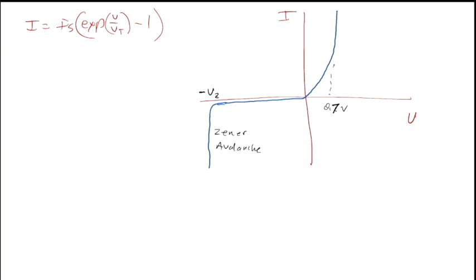There are different effects, and they occur at about the same voltage, and some devices have more Zener breakdown, some have more avalanche. Avalanche is due to having lots and lots of carriers, and they're all banging in and making more carriers, and the reverse bias is so high that carriers are quickly accelerated, and that causes an amplification of carriers, and you get this huge current.